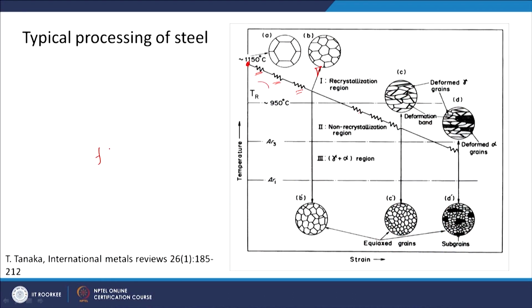They have different crystal structures, so their deformation behavior will be different. There is a lot of microstructural information, and these deformation processes have to be combined to get a very good understanding of the thermomechanical processing. And as we have already seen, we have to consider temperature, strain and strain rate, and at the same time there will be information about phases.